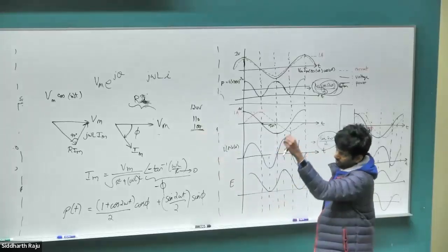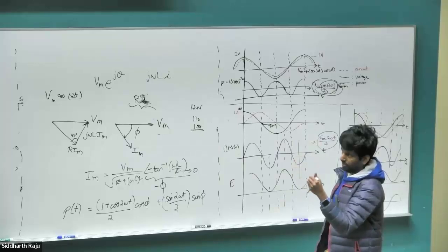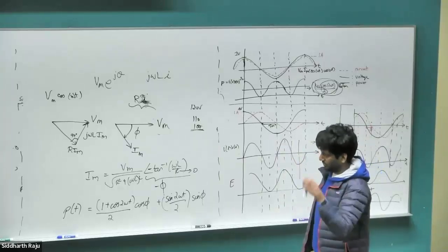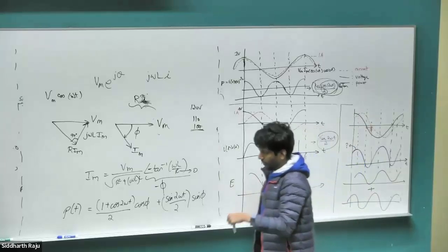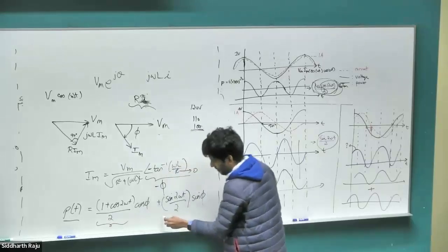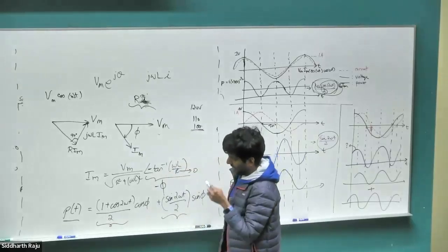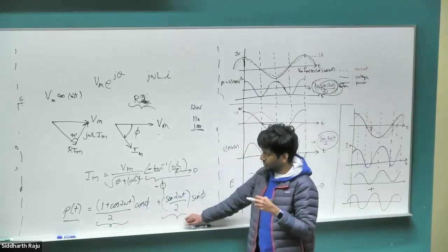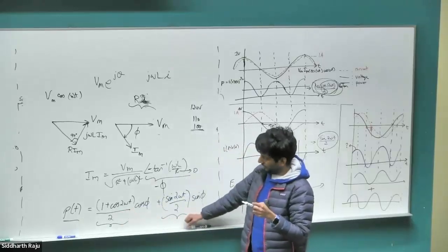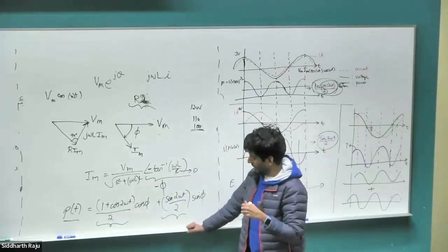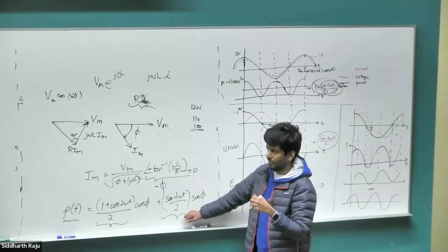The way we fix it is to put a capacitor right next to the load, across the load, capacitive compensation, so that the reactive power comes from the capacitor and not all the way from the transmission line energy source, right? So what we are trying to do is, when we have this RL node, we are breaking the power into two components. One power behaves as if it's a pure resistive network, another behaves as if it's a pure inductive network. This portion of the power is something we desire that needs to be sent from the energy source. This portion we usually try to avoid and keep local, right?